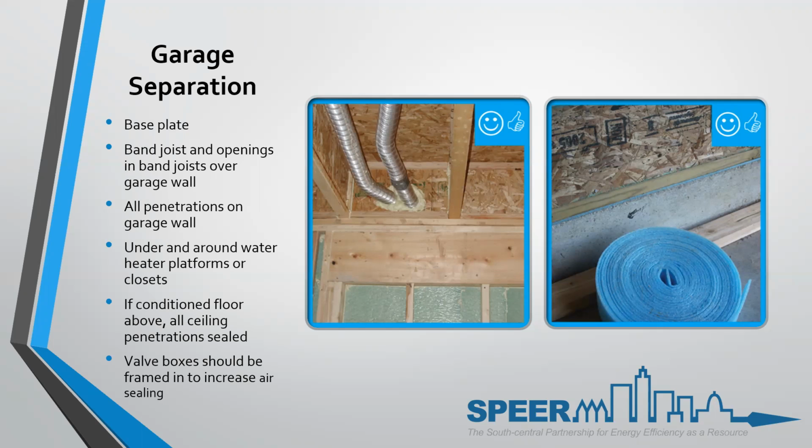The sill gasket or sill sheet or moisture barrier or moisture stop is what this gasket is titled usually. It's not always about air sealing, it's about moisture stop. But it also acts as an air barrier. So when you put it around the exterior walls of the rest of the house, that's great. It's a moisture stop, it's a moisture barrier, it's a moisture break, but it also acts as an air sealer. Same thing with the garage wall. You still need a moisture gap, a moisture break, which can act like an air sealing.